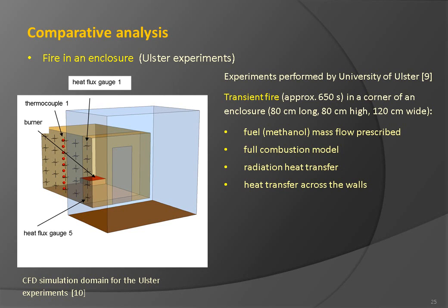The performed CFD analysis included a full combustion model, radiation heat transfer, and heat transfer across the walls. Temperatures were monitored at 9 vertical locations at the wall opposite the burner. In addition, heat fluxes were also measured at 25 different locations across the entire wall.